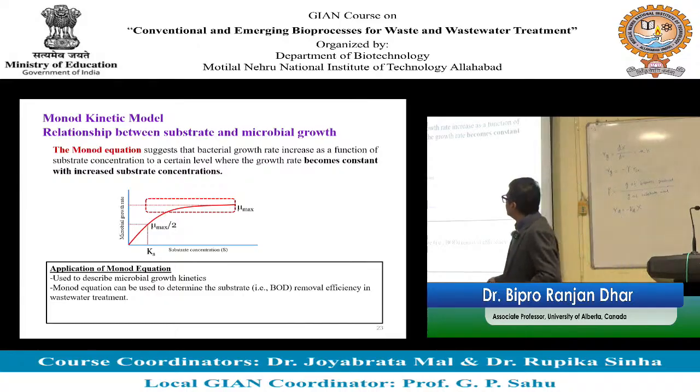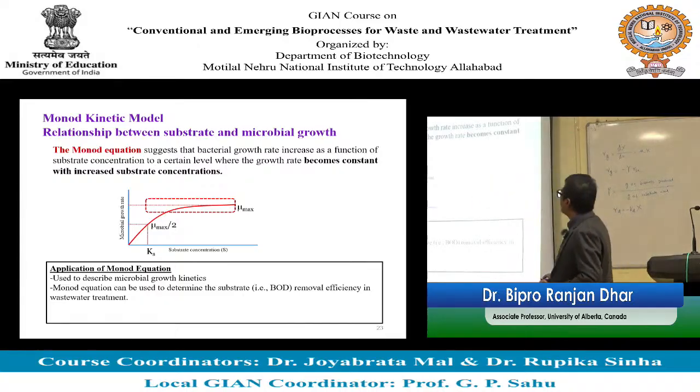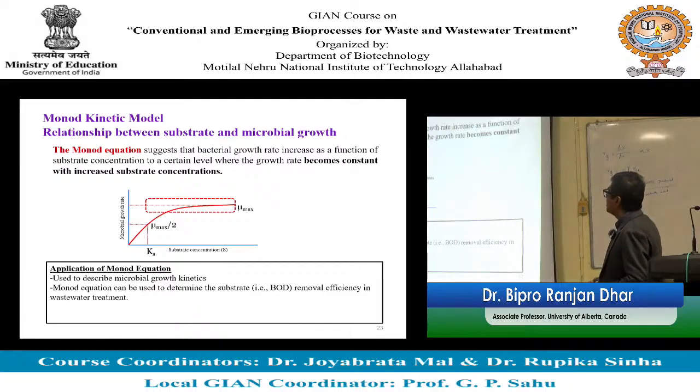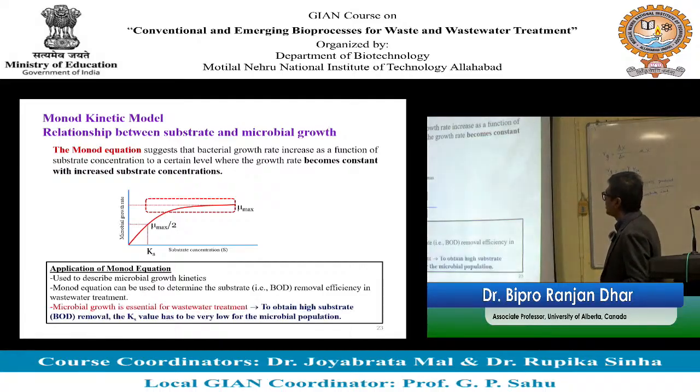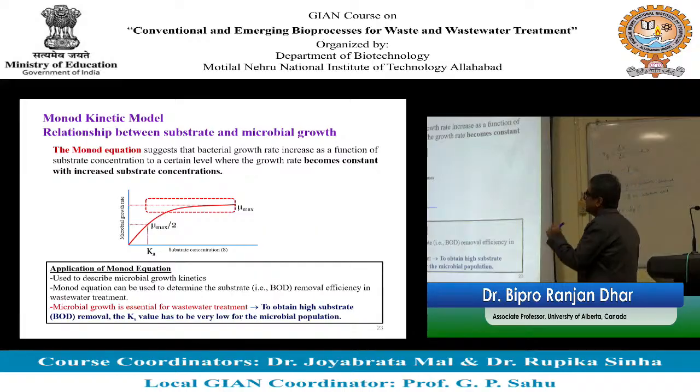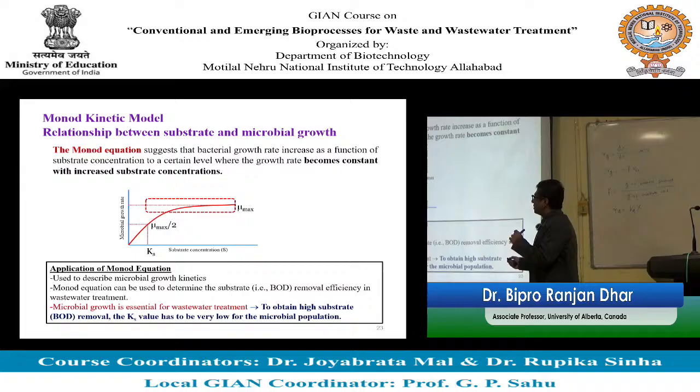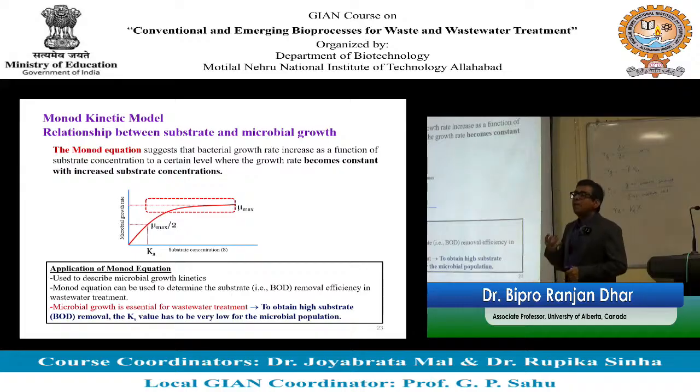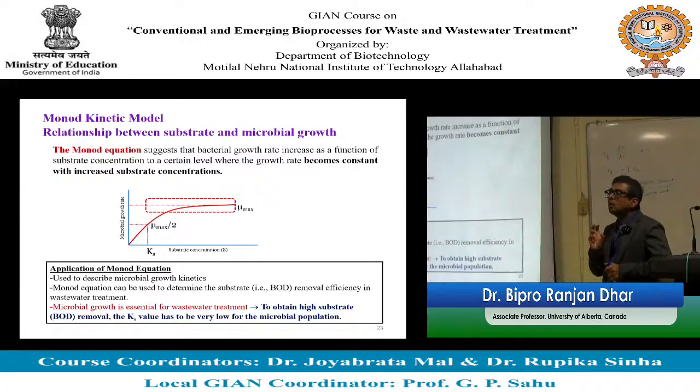The Monod equation can be used to determine the substrate concentration or BOD removal efficiency for a wastewater treatment process. Another key thing I want to emphasize: for a certain type of microbe, there is a specific Ks value.